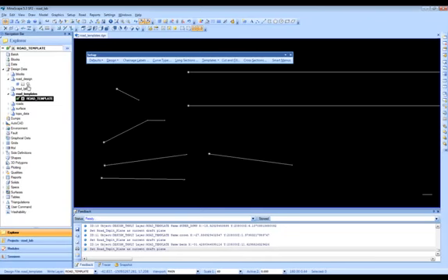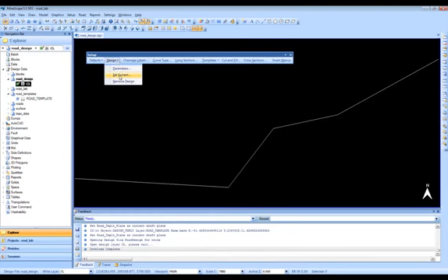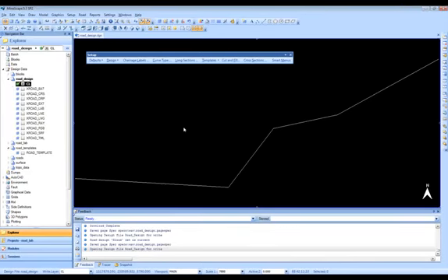Now I'm just going to go back to our road design file, and we can now get started. Now that we've got our setup complete, we can get started on our road design. And for that, we will first set our current road design. We'll set that to be our crossroad and say OK to that. Once we've done that, you see that MineScape Road Design has gone ahead and created these layers for us. And these are layers that our various elements of our road design are going to be located in.